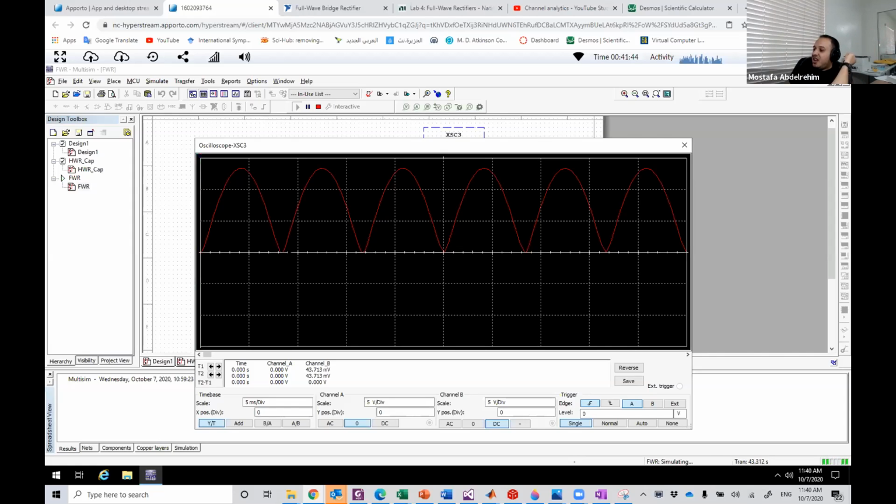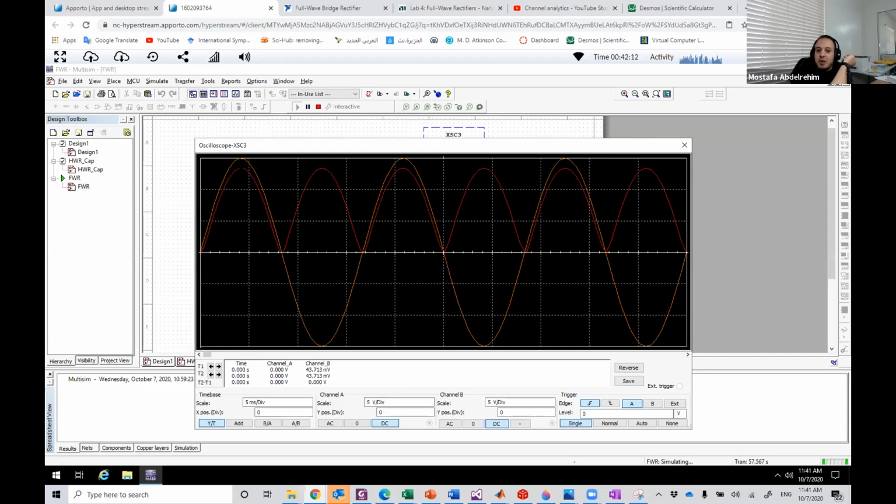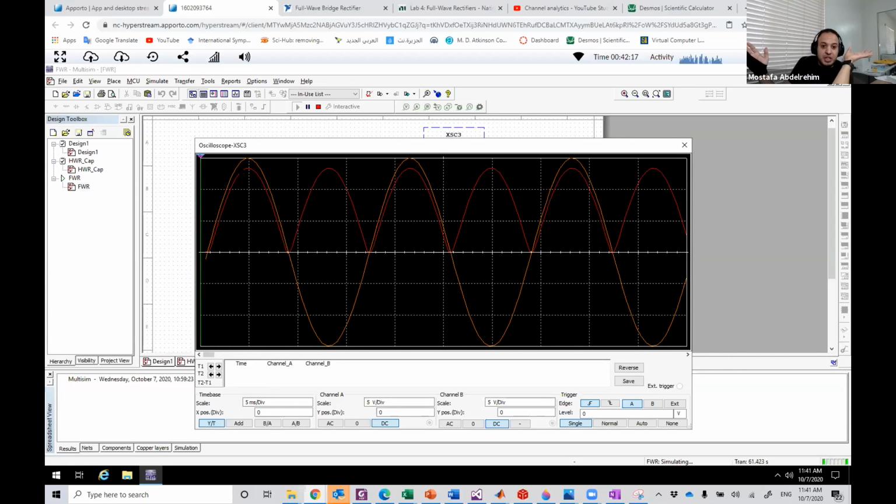And here is, guys, the 1.4 stuff. It's clear here with the full wave rectifier, and it was also smaller V maximum. Last time it was not clear because the V maximum was very high. It was 155.5. Now it's just 15. So it's clear now there is this small gap in which the diodes are off. And also it's clear the difference between the input and the output maximum. So this is 15. This is 15 minus theoretically 1.4. Here it may be 1 volt or something. Just measure it.